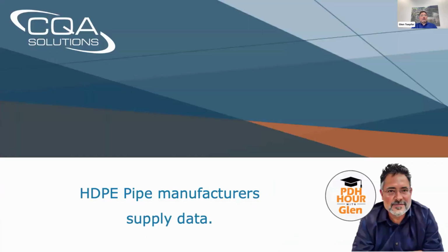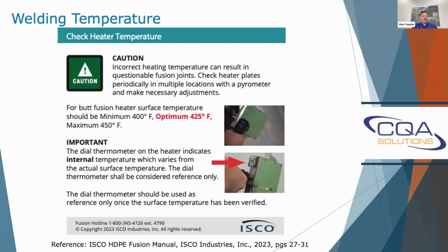Another reason why I believe that geomembrane manufacturers should provide the data is that HDPE pipe manufacturers supply this type of data. From ISCO Piping, I took this chart out of their HDPE Fusion manual just to illustrate, but they work with different equipment manufacturers, and they have 3 or 4 different equipment manufacturers and what the temperature, speed, and pressure should be.